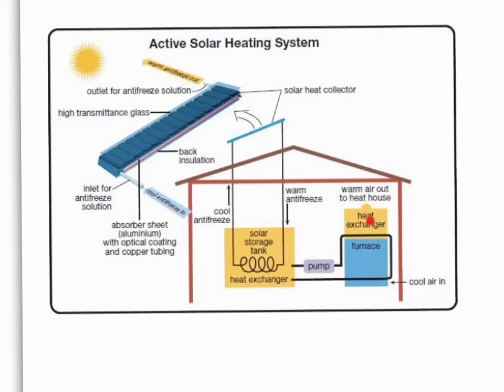Now, after its energy has been transferred, it goes back into the heat exchanger over here, gets redistributed into here where it's cooler because the energy has been taken off of here. Okay, so the energy from the sun causes this circulation, then it moves here, moves across, transfers the energy into the furnace, distributes it into the air ducts, and then the cooler fluid moves back into the system.